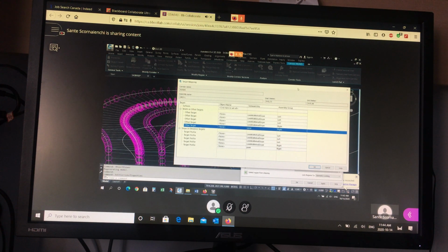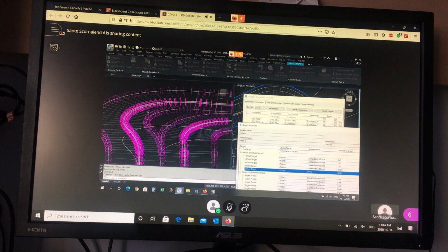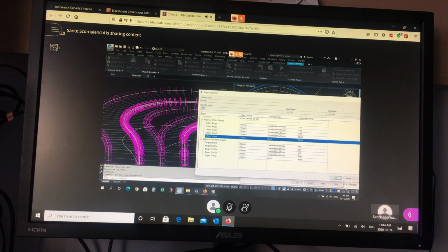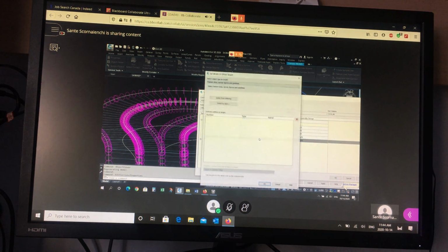First thing I'm going to do is say, hey, that piece, I want you to stretch it so that the end of it is exactly where the main road center line is. Okay, and you'll be able to see that happen in both views. So I'm going to say, okay, for this piece called pave, and ignore this, the horizontal, which is this piece here, right, the offset, I want this piece pave to match the alignment called center line of road, the original road center line.